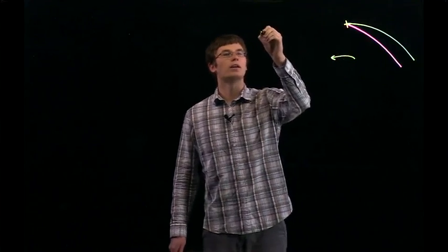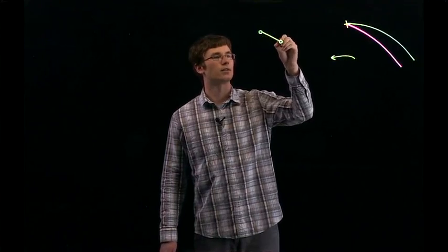As the whisker contacts an object, it is going to deform in some way. Let's call this pink line the deformed configuration. The goal of a good model of the whisker would be to predict what this deformation is and what the forces are at the base of the whisker right here, because this is ultimately what the rat senses. In order to understand more about the rat whisker system, we need to build a model of it. And the way we do that is to discretize it. We break it down into a series of rigid links that are connected by these joints that have rotational degrees of freedom.